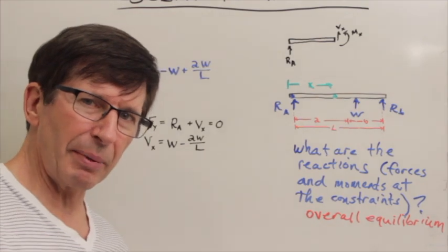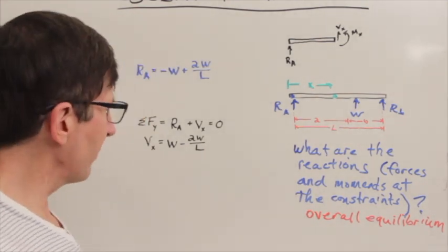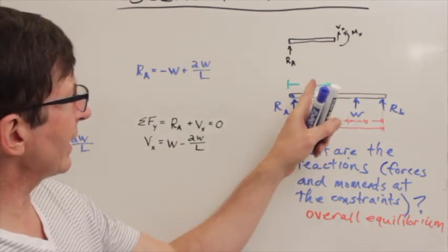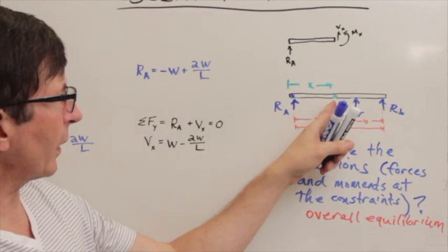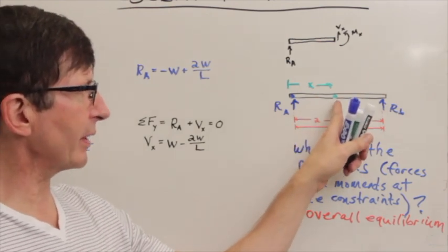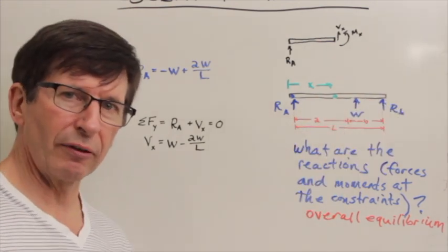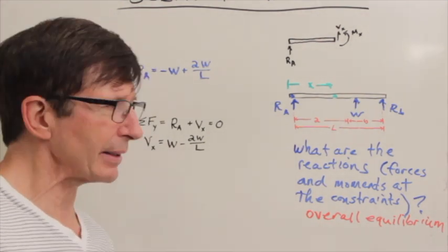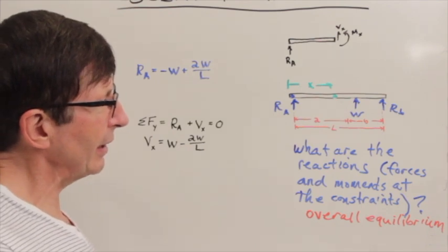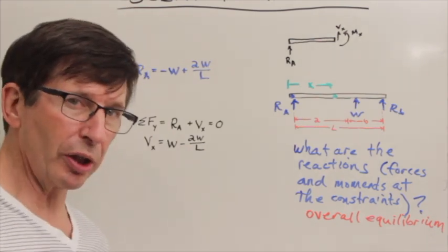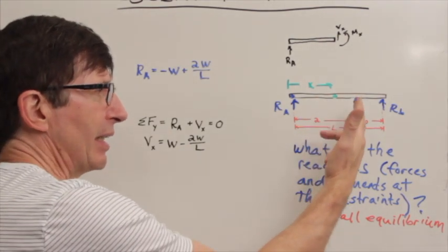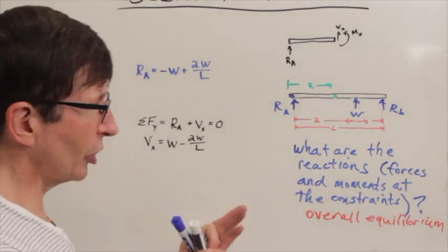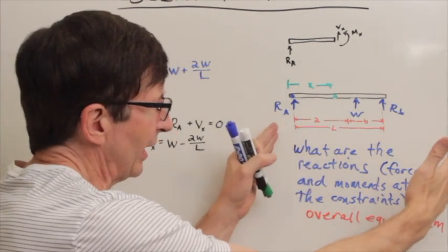One thing that's interesting about this cut-the-beam business is we realize that we will get a different equilibrium equation if our arbitrary point is to the right of where W is applied. That leaves us with having to remember that we have to make as many cuts as we have loading events starting and stopping down the length of the beam.